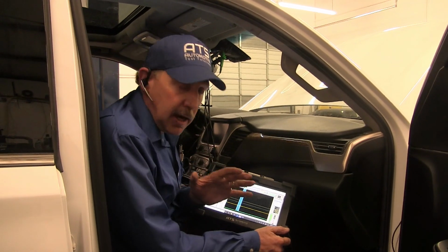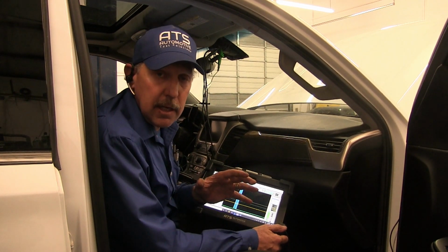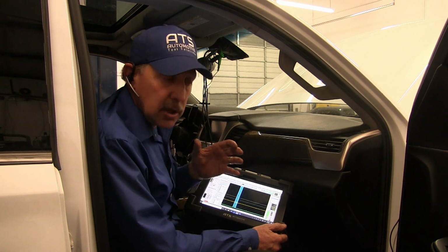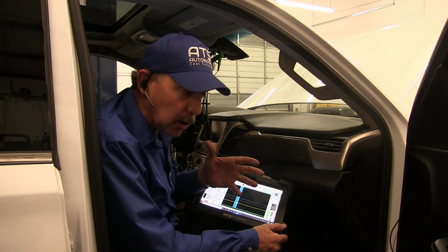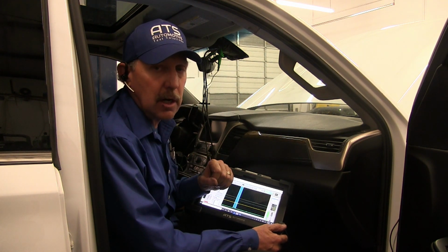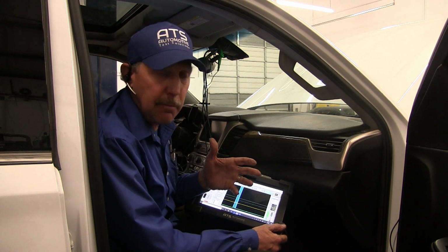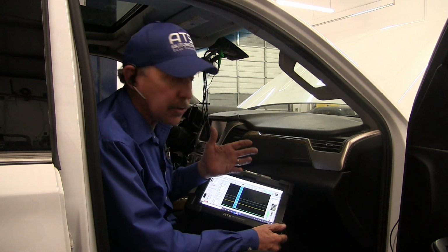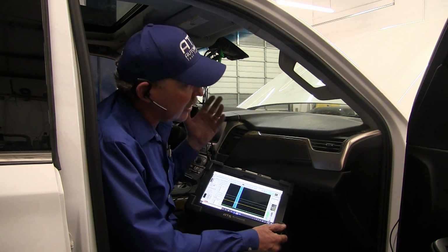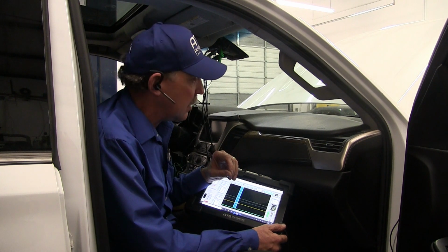Now guys, I hope you get the point of this, that you really need to look at the wiring diagrams, multiple diagrams, before we get started. Make sure there are no other wires that I can communicate to a module on, either through the scan tool or through some other system where that system is watching and we can be confused.